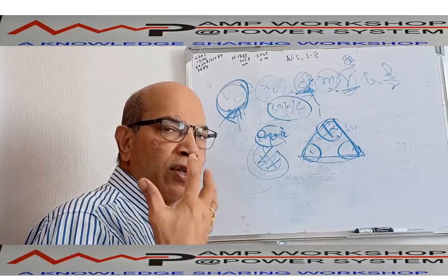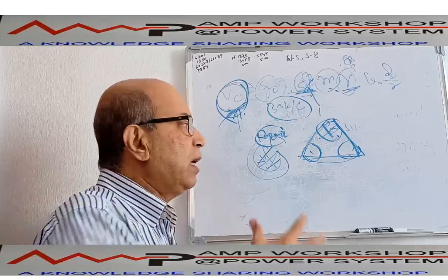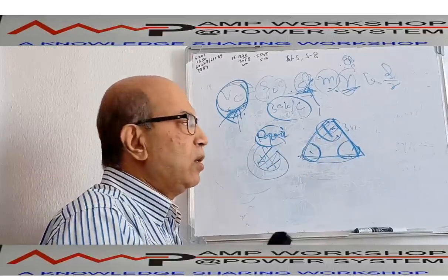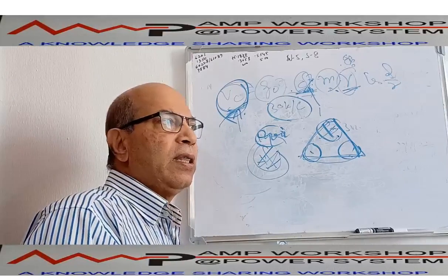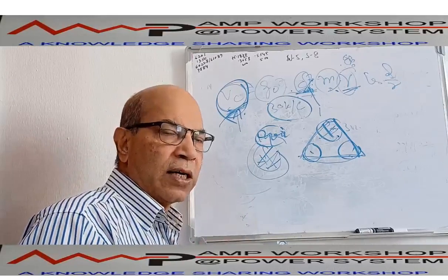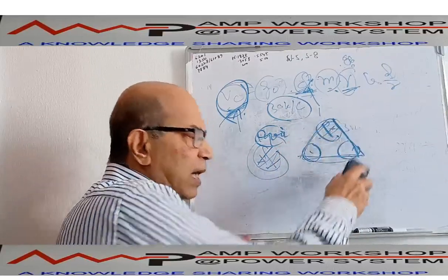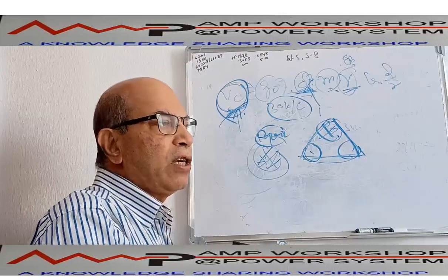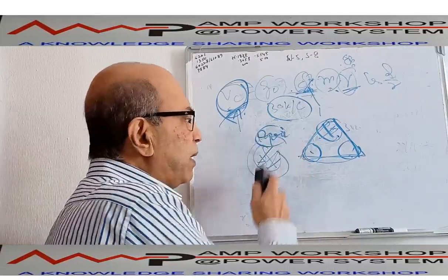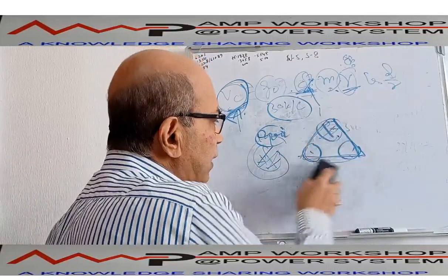because corona discharge is the wastage of energy, a loss of energy, so the energy loss will also be less. That's why for high voltage transmission, when the conductor size is very big, instead of using a single stranded conductor, we use multiple conductors connected through a spacer per phase. That will reduce the corona discharge. This is one of the purposes why corona discharge rings and these are used.